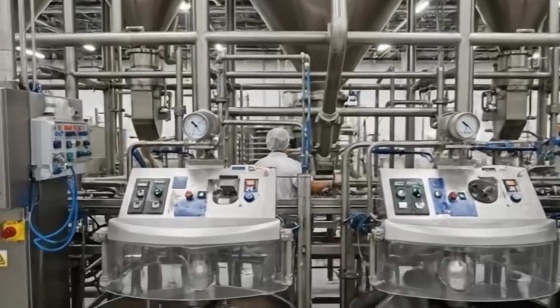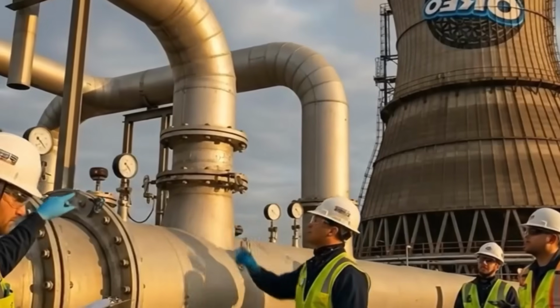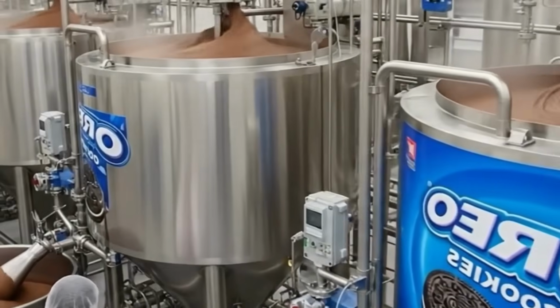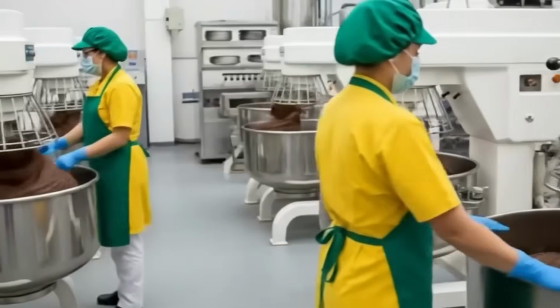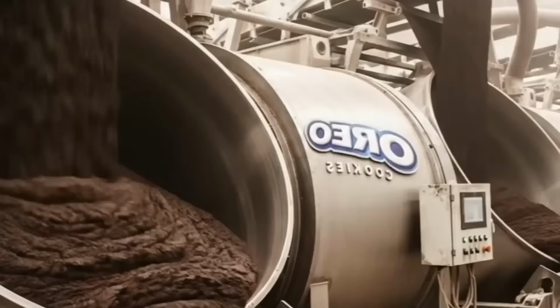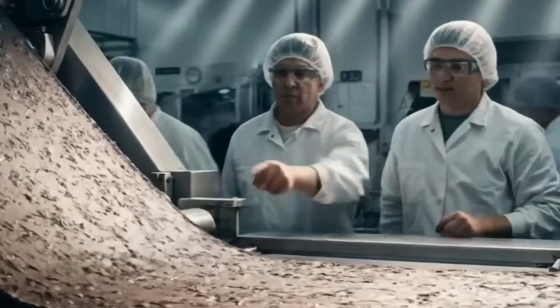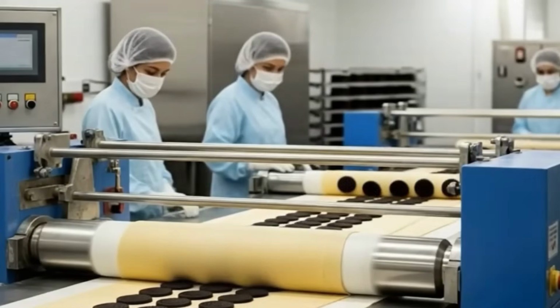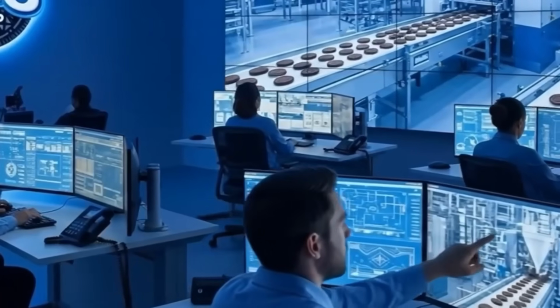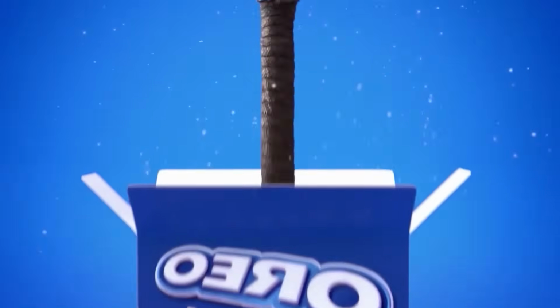Process validation occurs every production shift. Operators test dough rheology, sheet thickness, baking curve, moisture content, cream viscosity, deposit weight, roll hardness, and package seal integrity. Data is recorded in the batch record along with any machine adjustments or anomalies. All critical control points, including cream deposit temperature, bake time, and packaging seal strength, are electronically logged and must fall within specification limits or trigger corrective action.